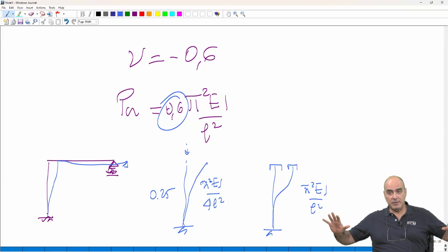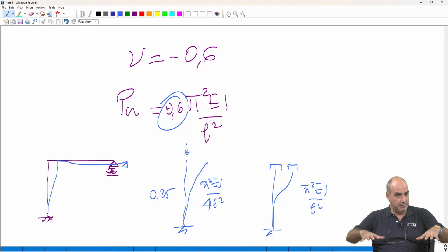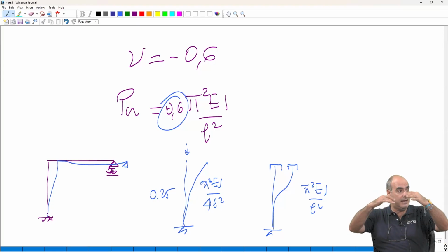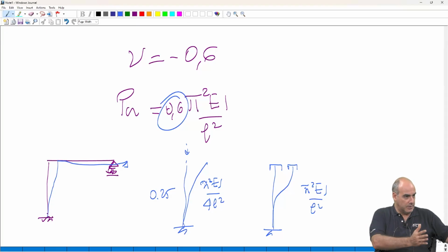So the two philosophies are, you want emulative connections? Okay, go ahead with that, but be ready for the fact that your construction will be slower, because you have first to install the elements, prepare them, then go for the connections, and also in order to continue the construction, you have to make the wet connection and wait until they settle down to develop enough strength. Pros and cons.